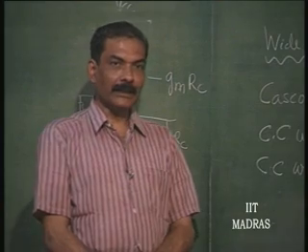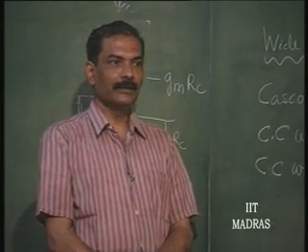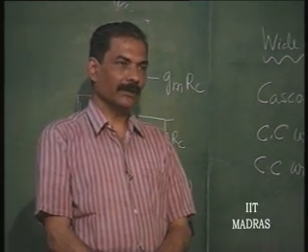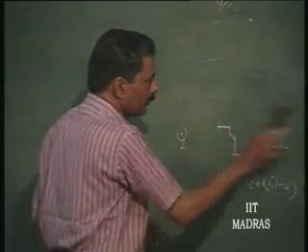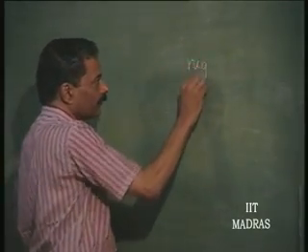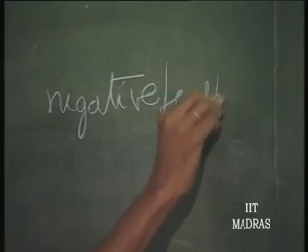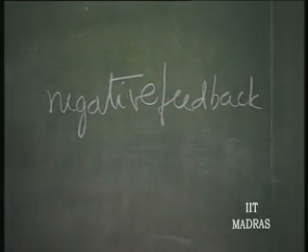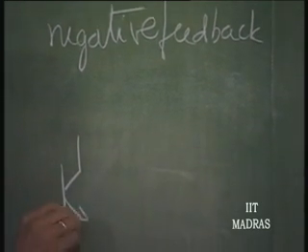We have, apart from this, negative feedback amplifier stages with local feedback, used for wideband application. This I have already discussed earlier. These stages, which are negative feedback stages, necessarily must have simple poles, first order or second order poles, so that they do not go into oscillation.